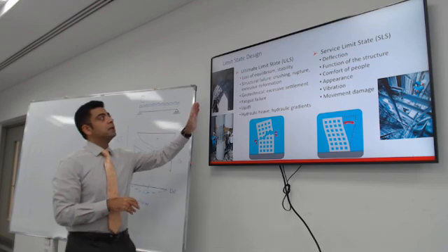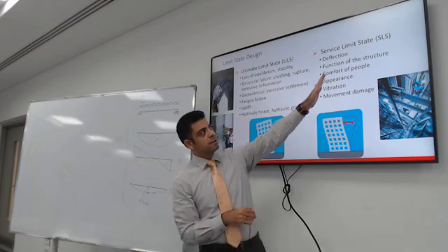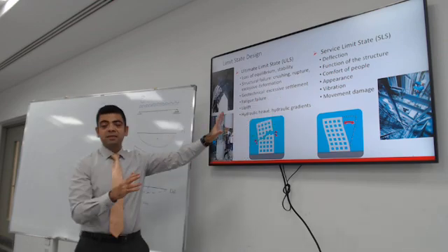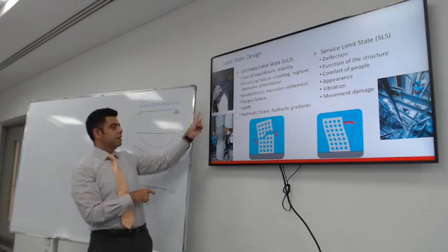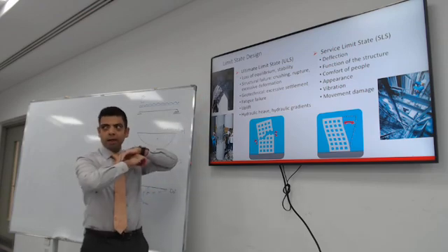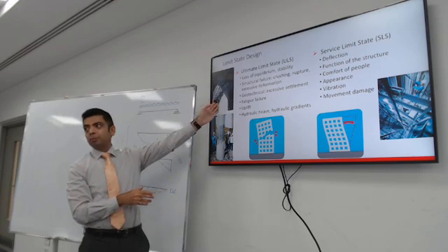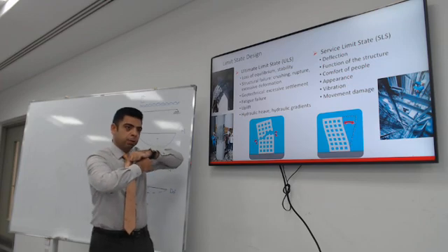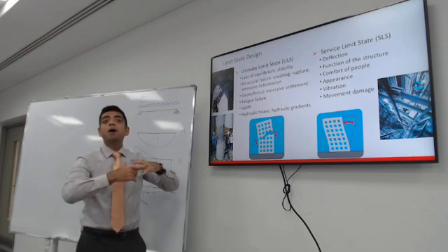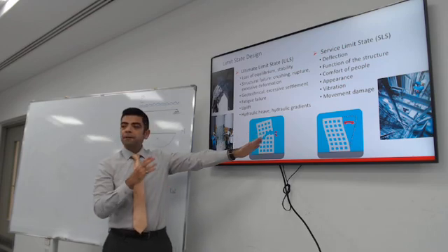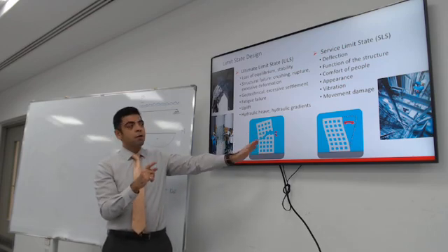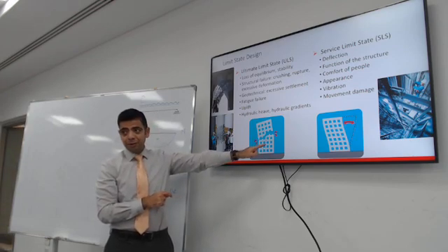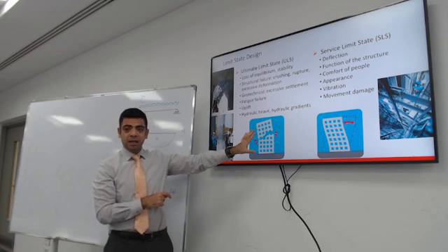So whenever the term ultimate limit state or service limit state come up, I want you to think of 2 different things. Ultimate limit state, this is the state of the building to avoid these pictures, to avoid a structural failure. This used to be a column. It was loaded so much to the point like the internal rebars exploded out of the side. That's the ultimate limit state. So if the building is not designed properly for ultimate limit state, you can result into failure. It's very dangerous to break this state of design.